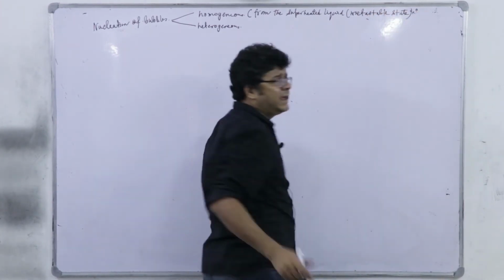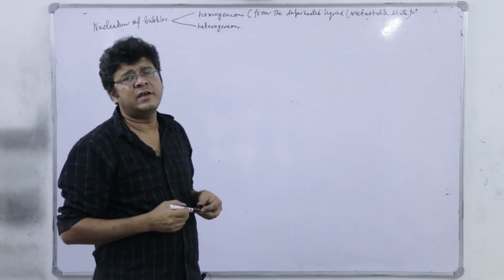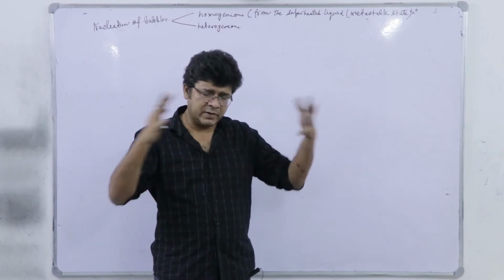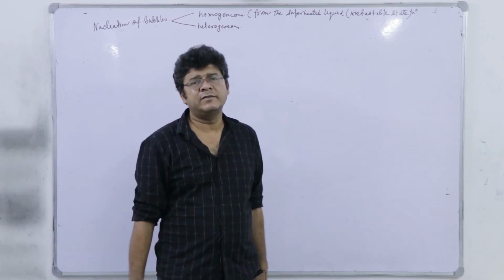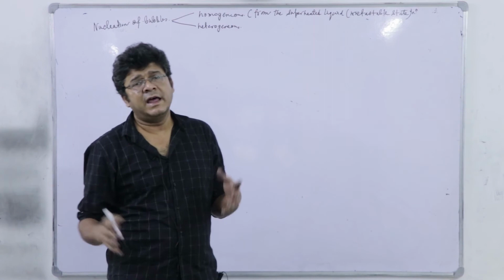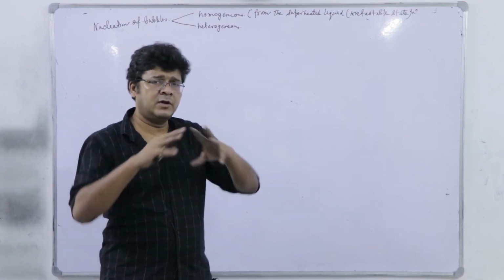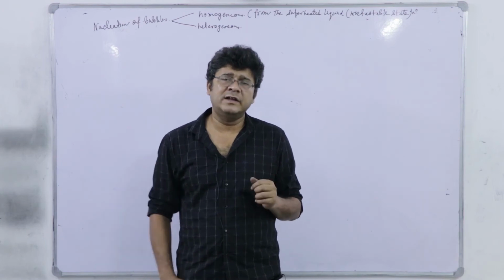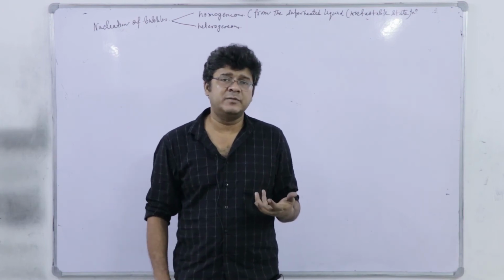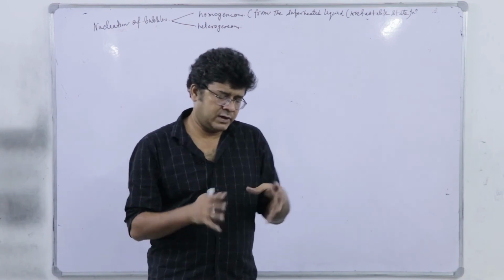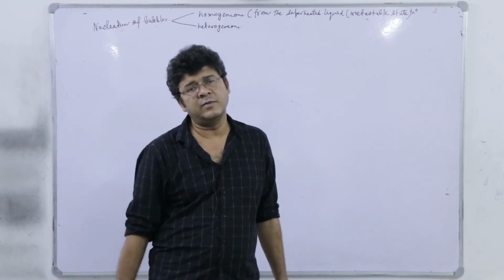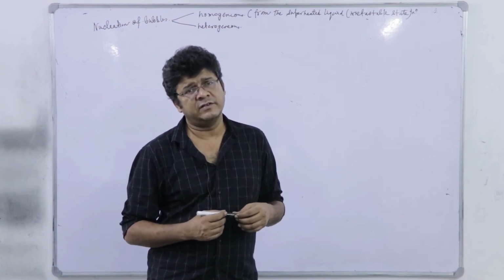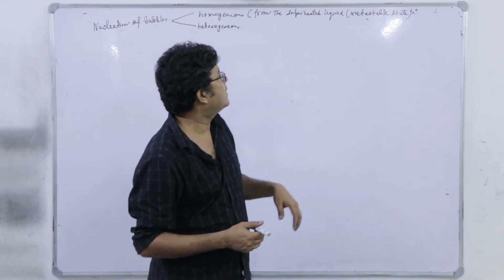So when we have a liquid whose temperature is above the saturation temperature, naturally from the bulk of the liquid we will have the generation of vapor bubbles. Like in an indefinite bulk of liquid, over a certain region, if I focus these high energy laser beams, it can happen that over this specific region the liquid becomes superheated and there will be homogeneous bubble nucleation. So this is typically the homogeneous boiling.